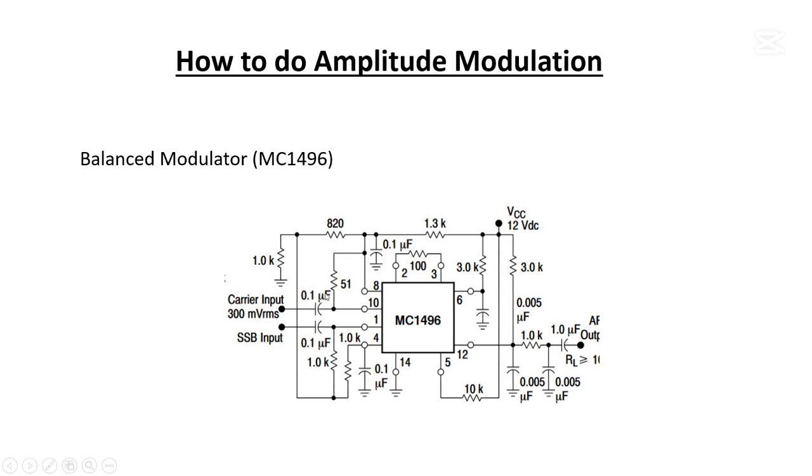Okay, so if you think in your mind what you can do here, you can actually add some filters so that you can take only the frequency between 500 and 3500 hertz, because this is the information. We actually have the information in this range.